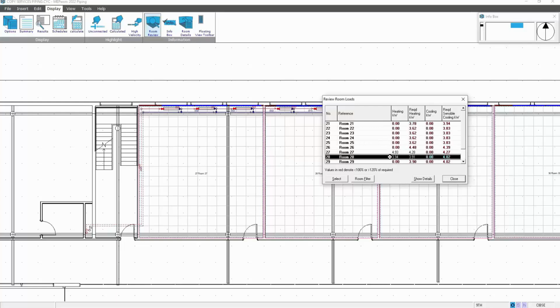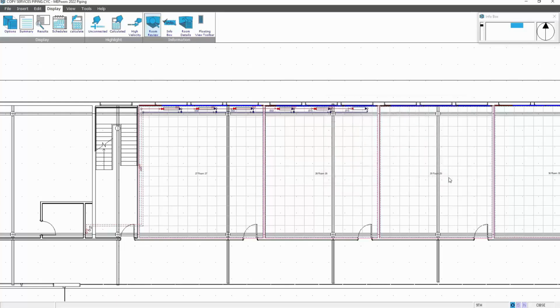It's quite easy to do, if you're copying down through the building, to not change the exposures of your roof externally to an internal ceiling, so you can see whether you have a shortfall in your heating output when you're placing your radiators. And you can see all the other rooms on this layout have nothing placed so far, so they're all showing 0. So the idea is to copy the services down through the building.